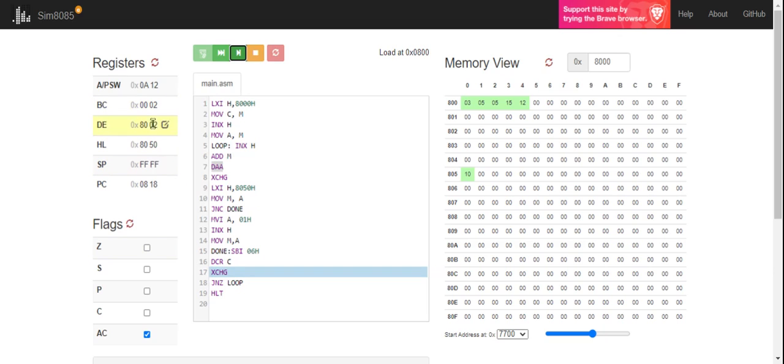Before that, what am I going to do? My next input is available where? In 8003. So what should happen? When I give this INX H over here, please remember, when I come back into this loop, when I give INX H, this 8050 will be updated. It will not be 8002 which will be updated to get the next input. So in order to avoid that, I'm giving this XCHG over here. I hope you now understand why I gave these two XCHGs over here.